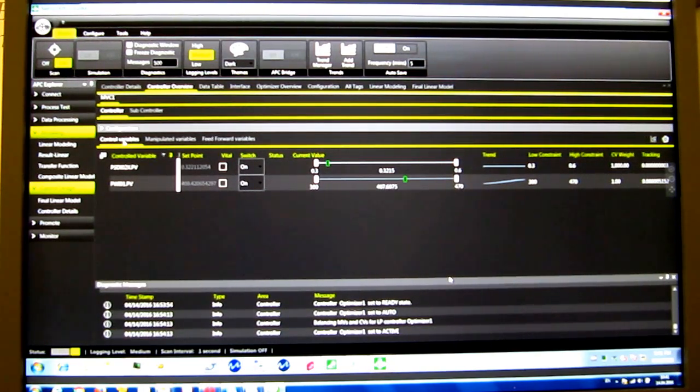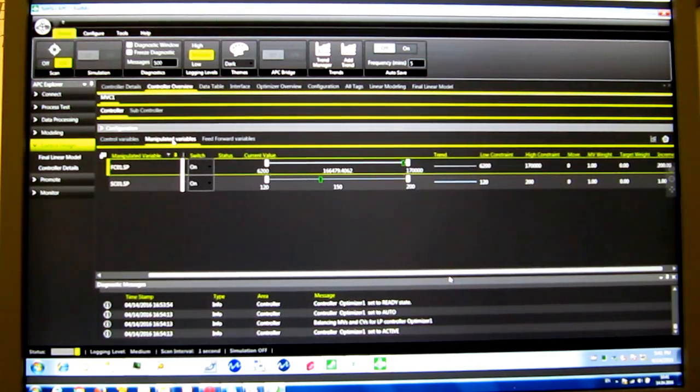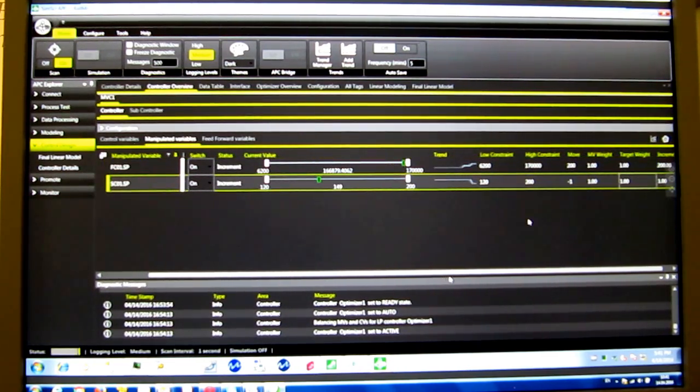Now, from the operational point of view, the most important thing to understand is that for control variables, CVs, or manipulated variables, MVs, the operator will have high and low limits. And those are the boundaries of the process. So the first objective of the APC application, using the model, is to keep everything within the specified limits, within that boundary.